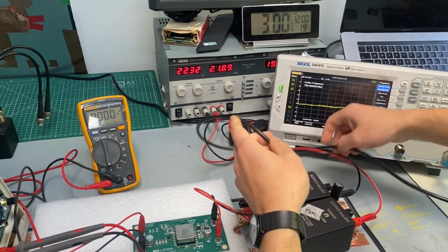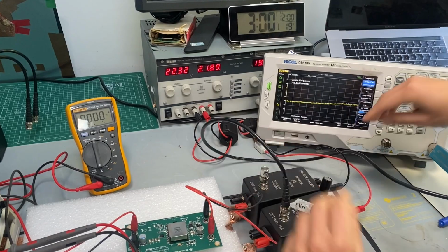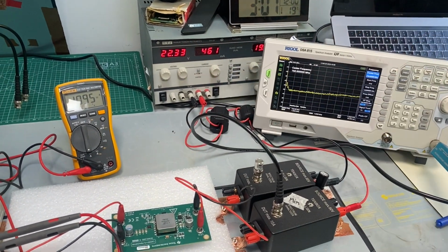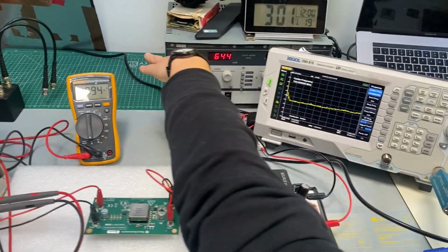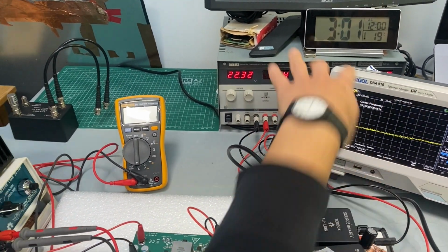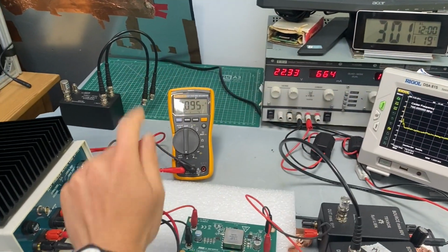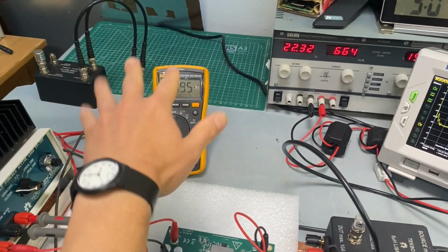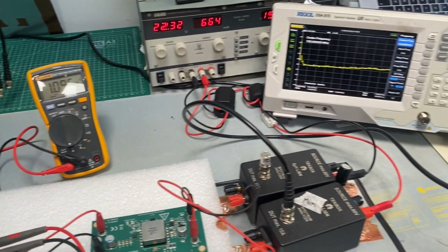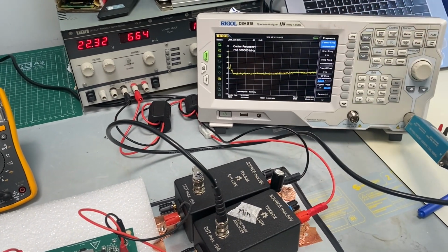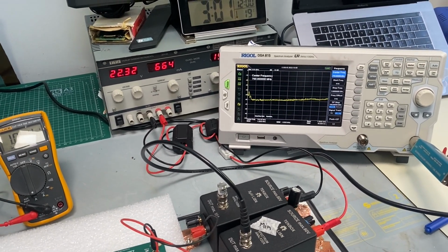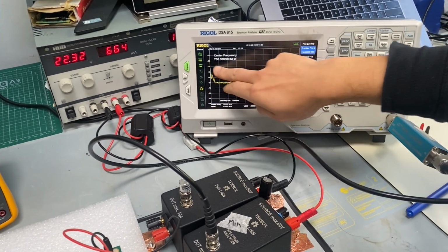Okay, and now we are measuring the LISN output using our spectral analyzer, as you can see here. So I'm going to switch on the power supply unit, and you can see here we have 22 volts input voltage and about 663 milliamps as input current. On the output, we have about 1 amp DC current measured on the low side. Okay, and our spectral analyzer we set at preset, so that's how you get it when you power it up from the manufacturing setup. As you can see, you already can see some noise observed here.